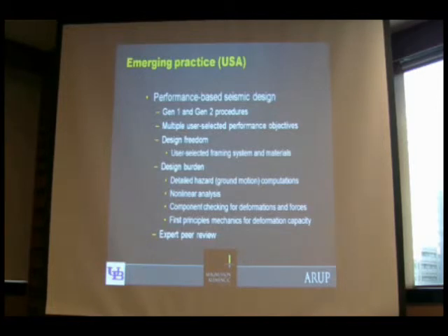And I've listed some of the design burdens here, namely one has to undertake detailed seismic hazard computations, often undertake nonlinear dynamic analysis. We use component checking procedures based on the deformations, not forces, and there's a significant attention paid to first principles mechanics that takes us all back to our university days.